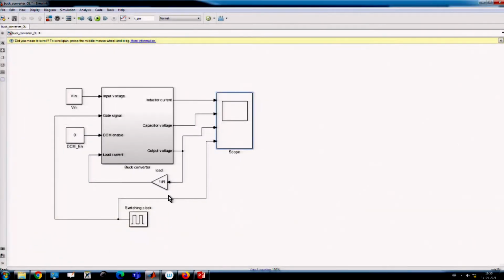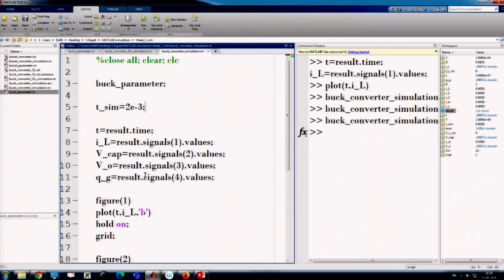Then how do I change the resistance value? Okay, next question. Now doing all these things, you have to go back and forth to the Simulink file, do changes, check there, take the values. Why should you do that? First of all, if you want to plot in Simulink, that itself will take time, because Simulink plotting while it is running will actually take more time than if you run it and plot it after the simulation is over. You can store it. So this is possible.